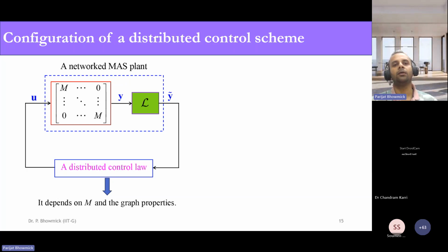When we go into the second control course, in some universities they offer two control courses, or even in universities where the UG students have only one control course, those who have the control specialization in their PG curriculum are taught advanced control courses, where advanced control starts with modern control. So the first topic taught in modern control is state space analysis. State space analysis gives us the advantage that instead of considering only the output feedback, if you can also take the feedback of the other variables of the system, then you can always have better control or better grasp on the system. So that is the main difference between state feedback control and output feedback control.